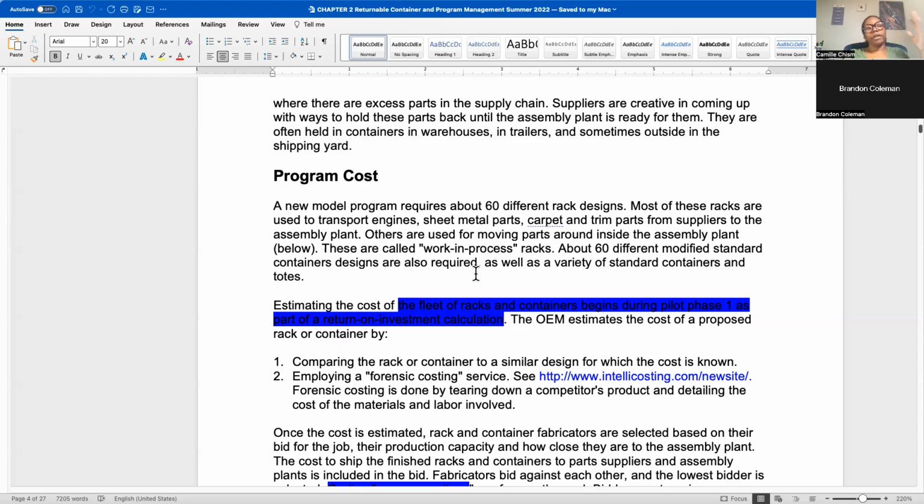How many parts are you going to have? Are you going to have roughly 6,000 parts? Roughly 300 parts? What are you going to have? So that will help you to determine, I'm going to need 300 different packs. Now you may end up using the same standard bin for 50 of those parts, and then your dunnage may be different, or how many parts go in there, but it can help you plan to say, out of my 500 parts for this particular product, or 1,000 parts for a product,